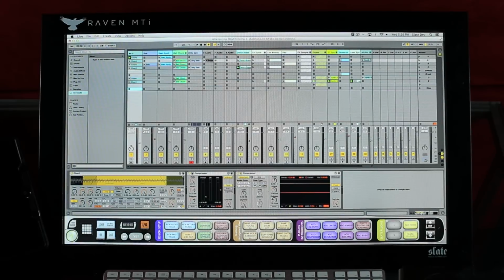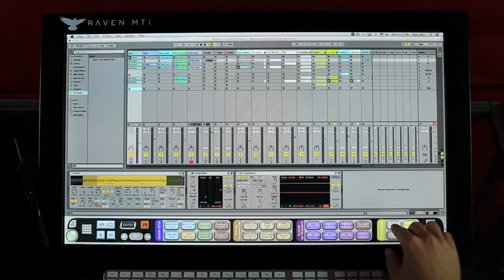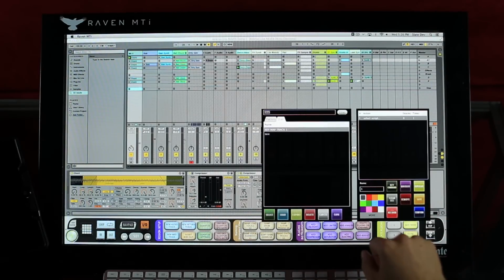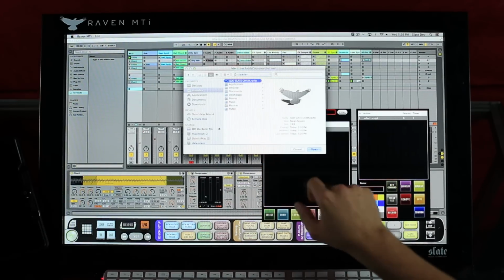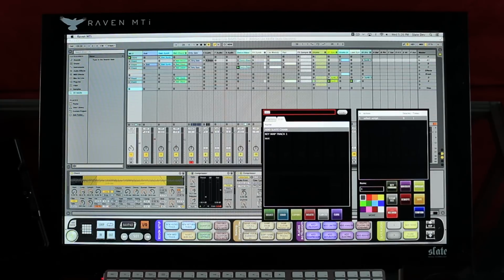Importing a batch command is simple. In the Batch Command System menu, hit Quicklist and select the User tab from the top. Now, hit the Load button and locate the .ravbc file on your computer. Select the file, and Raven will import the file into the User tab.